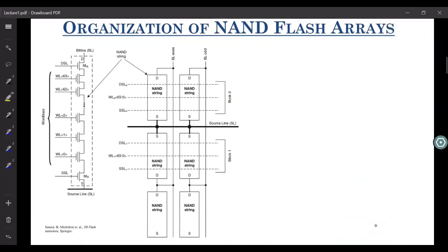In the last modules we were looking at the floating gate cells, how they can be arranged to form NOR flash memories or NAND flash memories. Then we were also looking at their program and erase characteristics, the different physical mechanisms like Fowler-Nordheim tunneling, channel hot electron mechanism. We also looked at UV erase, and we were also discussing reliability concerns like SILC, the endurance failure and those mechanisms, and the defects, how they can be introduced in the tunneling oxide layer.